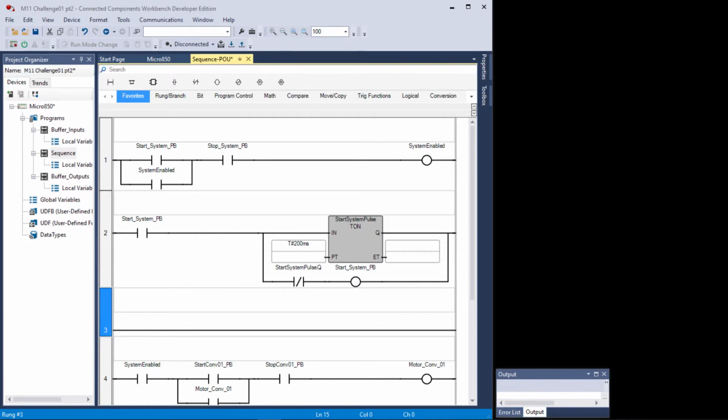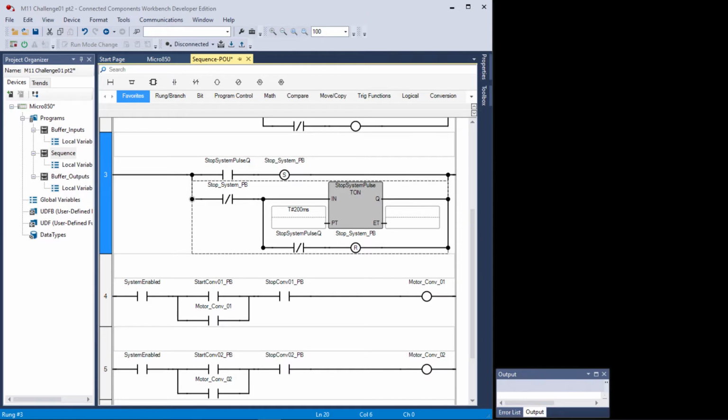And then you should probably toggle all 3 just for your own edification. Now remember that the action of a normally closed push button, like the stop button, has the exact opposite sequence as a normally open button, like the start button. So the stop button is on, and when we toggle it, we want to toggle it off, but then we want it to come back on.